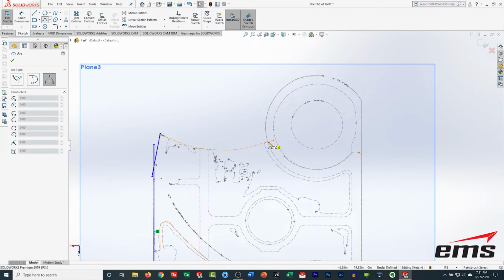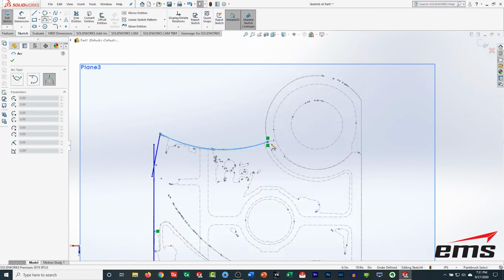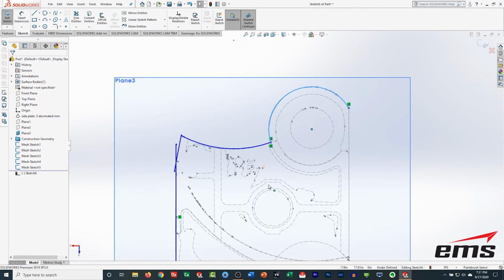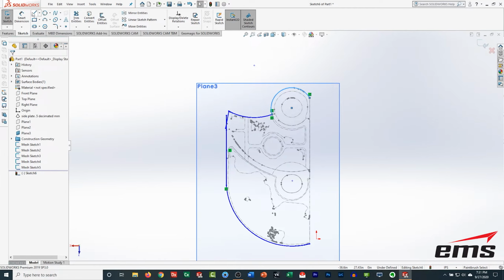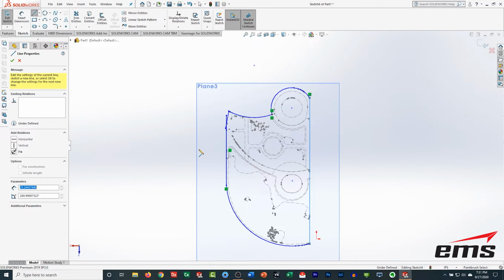Now you can also add dimensions to all of this, because again, these are just SolidWorks sketches. So if this radius is 48.492, you may decide, hey, I'm going to just make that 48.5. So you can kind of override this. You can fit geometry and then add dimensions if you want, or add constraints like parallelism, make it perpendicular, whatever it may be. And then we'll come down here and trim this. But this is the basic concept all the way through what you're going to see here.